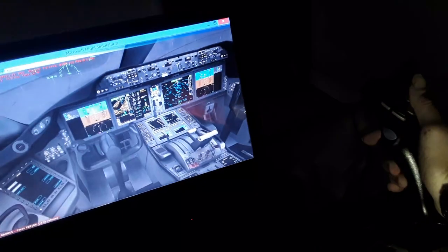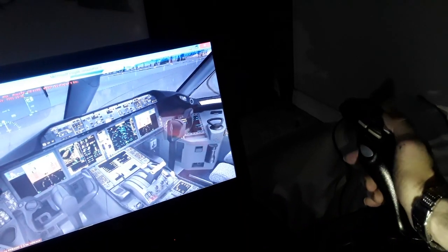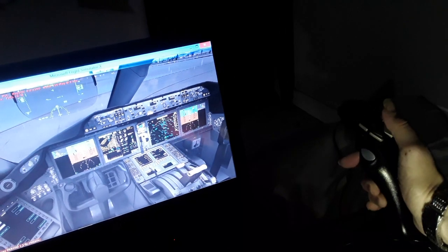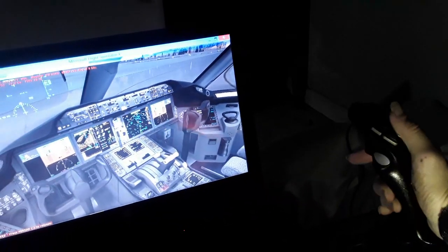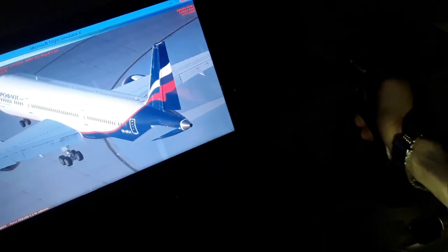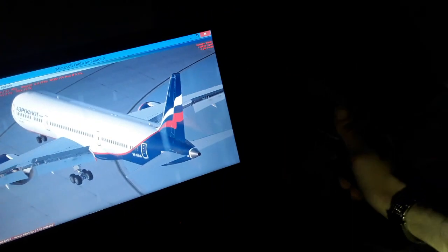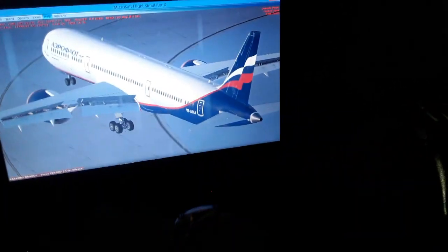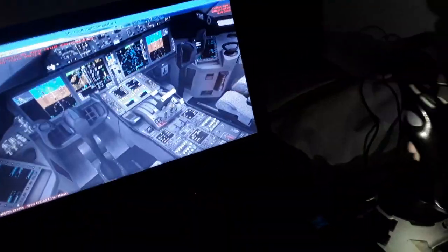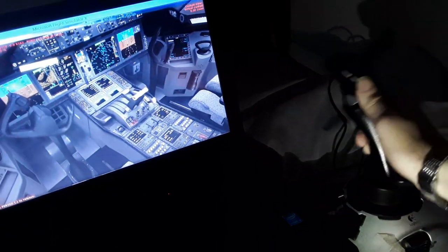They're also interconnected, the rudder pedals and tiller. Also the rudder is aerodynamically effective at about 45 knots in takeoff. You can see the rudder here for making yawing turns, ailerons and spoilers. Also very important, bank roll turns. And the elevator, as you can see, the elevator for climb, for descent, making turns to the right, control wheel.